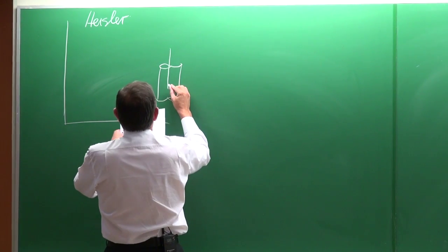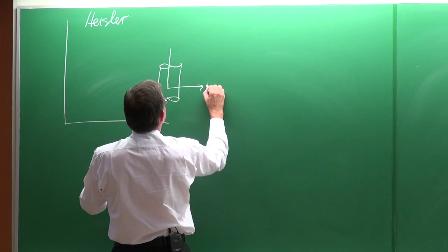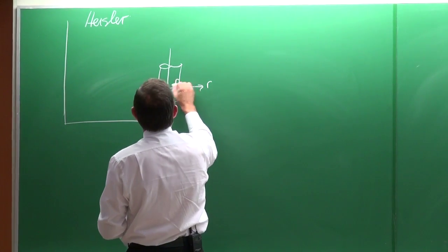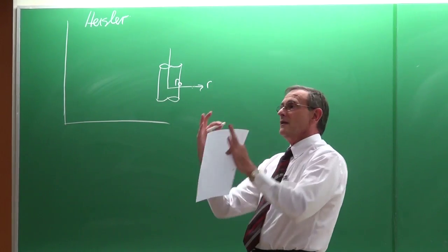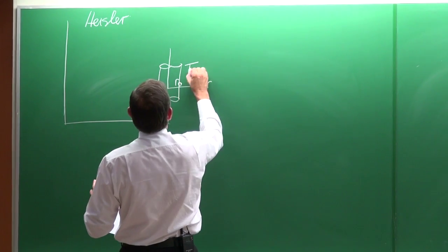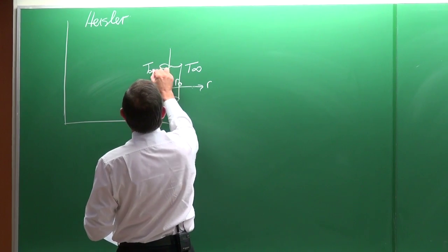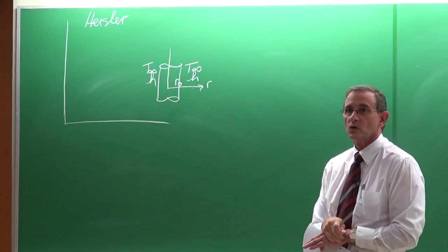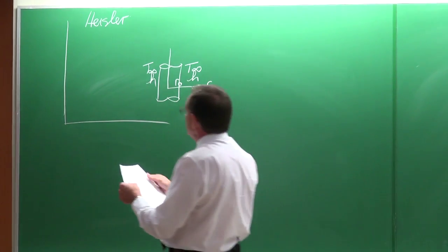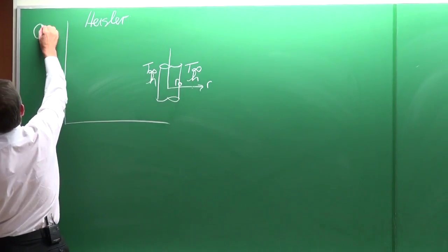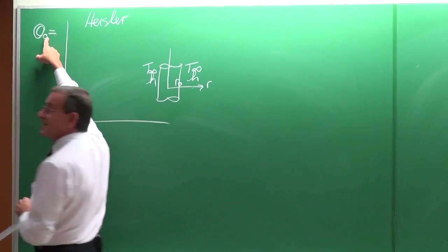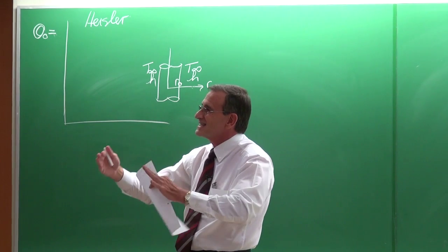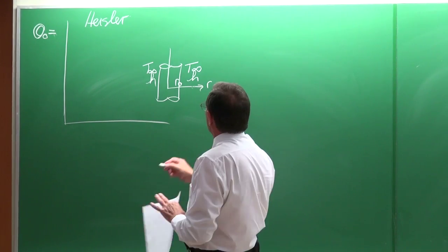And on it, they will show you typically the coordinate system, that is equal to r, and the radius would be equal to R0. And then they would also show next to it, there's the environment temperature, and there's the heat transfer coefficient. Okay. And on this axis, typically with the first graph, they have theta 0. What is 0 again? 0 means in the center of the body. Where would that be?